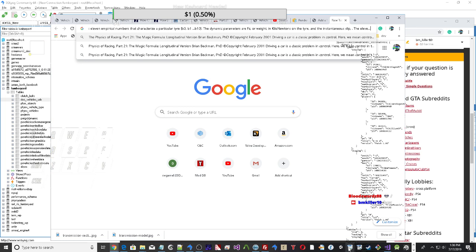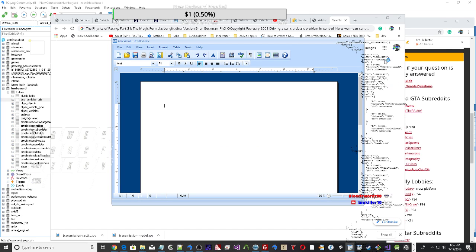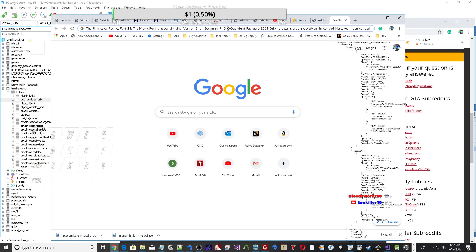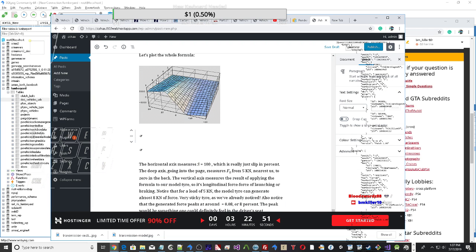Vertical suspension travel. suspTravelDirections[i] = PxVec3(0, -1, 0). Wheel center offset is offset from rigid body center of mass. wheelCentreCMOffsets[i] = wheelCenterActorOffsets[i] - chassisOffset.